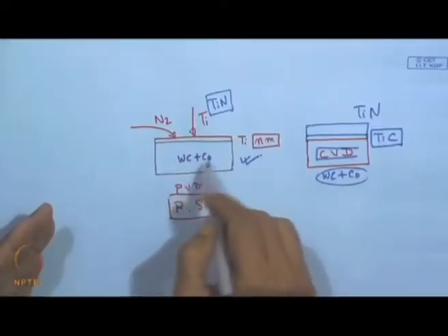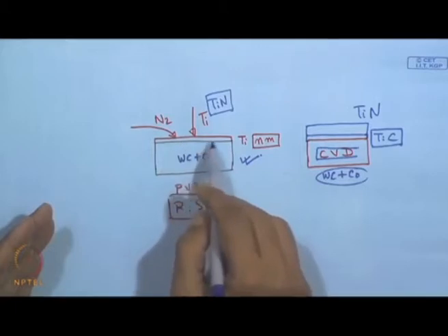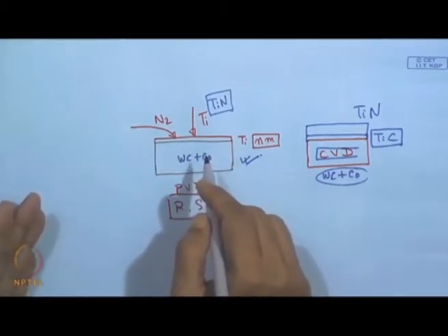Parameters means the cathode voltage, then the system pressure, and if it is an unbalanced magnetron, if provisions are there, then also the ion to atom ratio of the incoming flux towards the substrate, because it is very important to establish one of the strongest interfaces just over the substrate surface, and over this interface the whole architecture will be built.